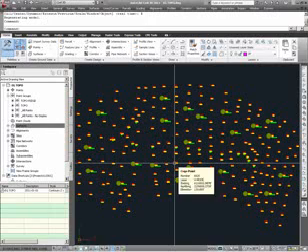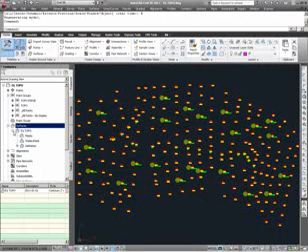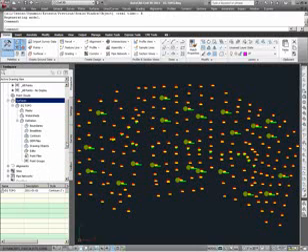Upon choosing OK, looking under Prospector again, I now find that we have the EG Topo surface which we just created. Now the creation process we just took is only to create the entry for a Civil 3D surface called EG Topo. We do not have a built surface at all, nor have we defined any surface data to the EG Topo surface. So that's the next step.